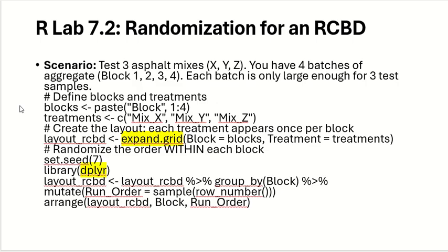Soil, but not in detail. But the point is, you will take aggregate from a sedimentary rock. If it fits the size distribution, you will take it for design. But it doesn't mean that the properties of a sedimentary rock are the same as granite. So these things also affect. So 4 batches, all 4 of them are fit for use because of their size. This is where we are stopping the criteria, but there are other things as well.